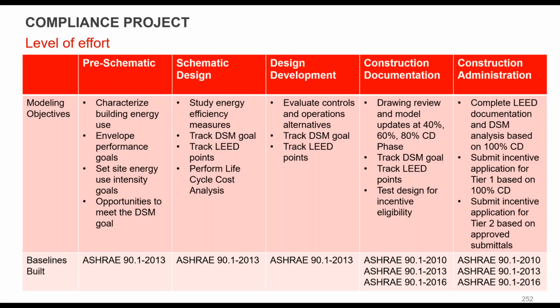So the level of effort, you'll see the baselines: we've got baseline through schematic, pre-schematic, design development, and then in construction documents, we add the others to be able to look at that. So the objectives for pre-schematic: characterizing building use, getting envelope performance goals, setting site intensity use goals, and opportunities to meet the DSM, design demand side management.